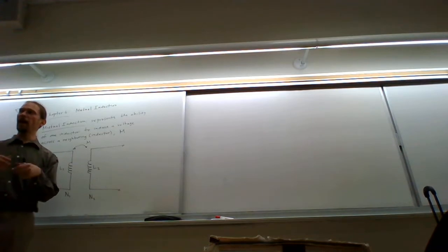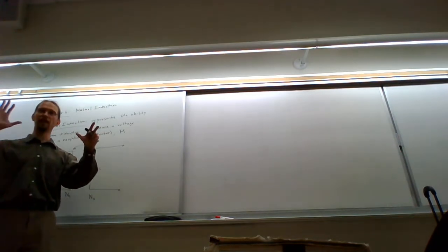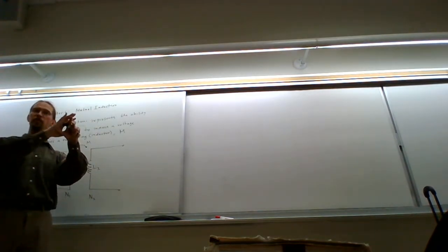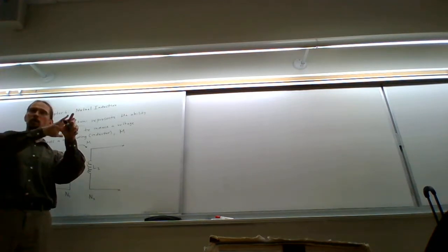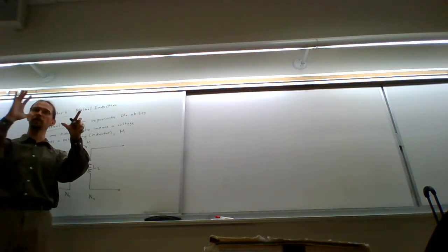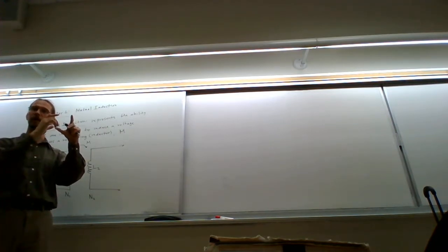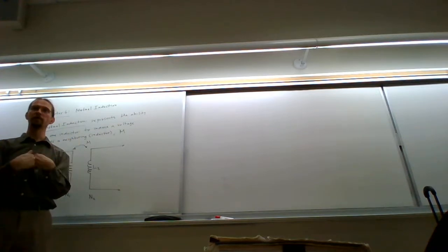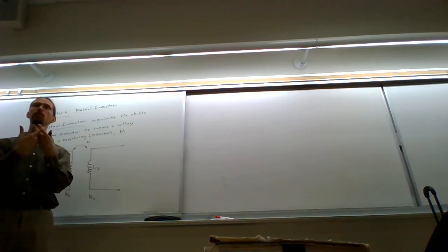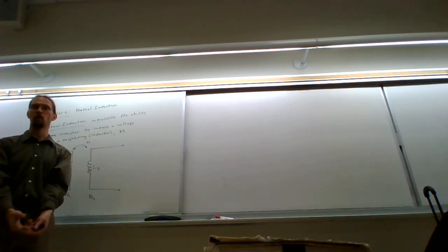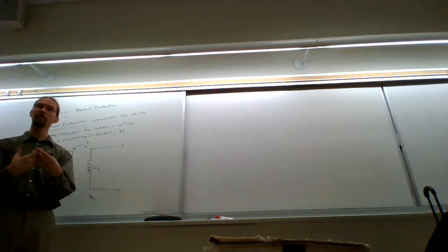As magnetic fields pass through coils, there's a surface area across those coils that the magnetic field passes through. If you take the product of the magnetic field strength times the cross-sectional area, you get what's called a magnetic flux. And if you have a time-changing magnetic flux, it induces a voltage across the coils. That's how we derive the IV characteristics for an inductor.